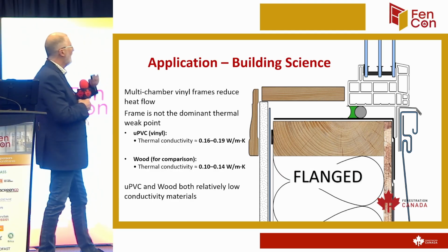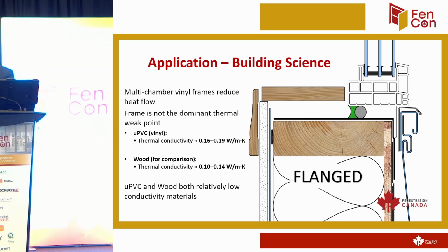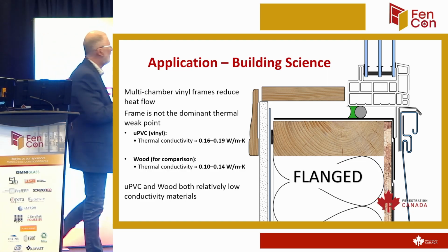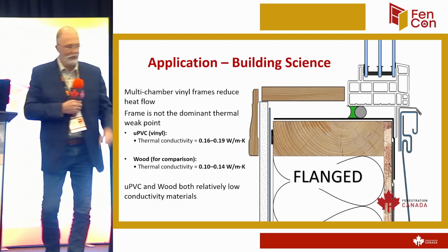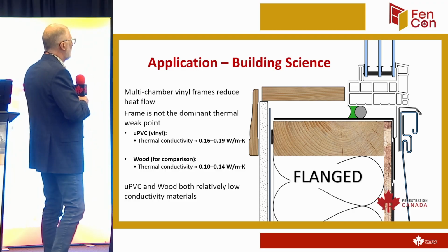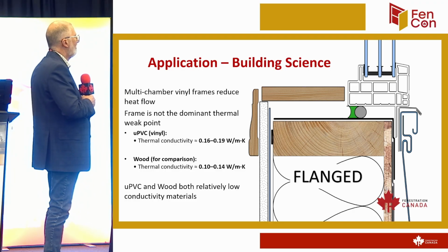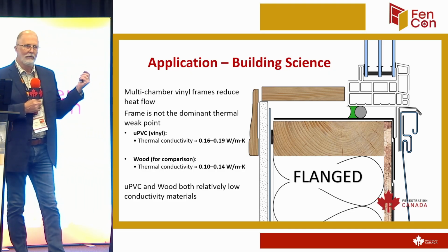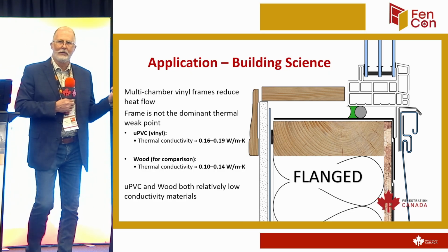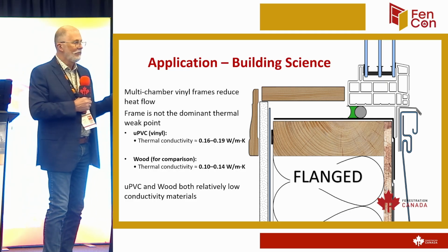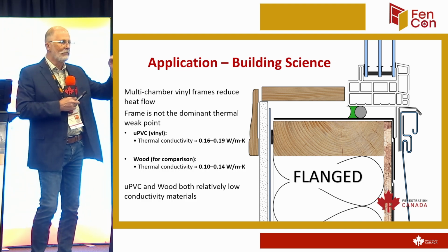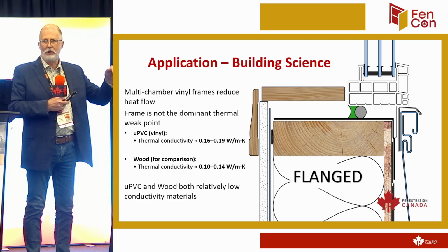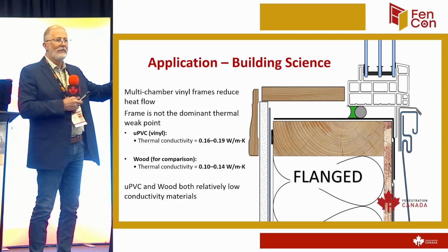So when we apply the building science, and we look at what this is telling us, it's telling us that when we look at a window, for instance, a PVC window at 0.16 to 0.19 watts per meter per Kelvin, or Celsius, depending on what you work in. But if you look at the temperature difference between that and wood, very similar. So even though the test was done on vinyl windows, the wood has a very similar thermal conductivity. So when you think of the materials and the air in the house reaching those materials, it doesn't take much to hold the temperature warm to reduce the condensation, as long as you don't have air leakage